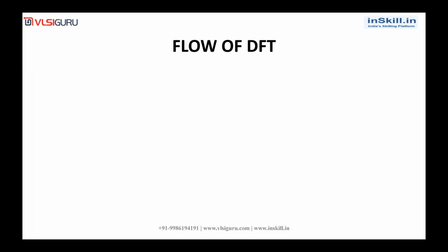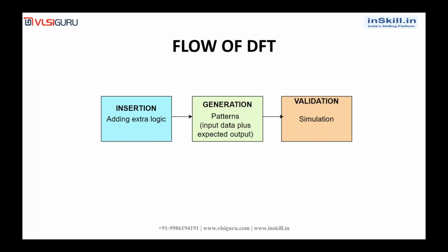Now we will see the flow of DFT. First we have insertion. Insertion is adding extra logic. As I had already told, we will be adding some test structures into the design, like scan insertion, memory BIST insertion, boundary scan insertion. That is what is called adding extra logic.